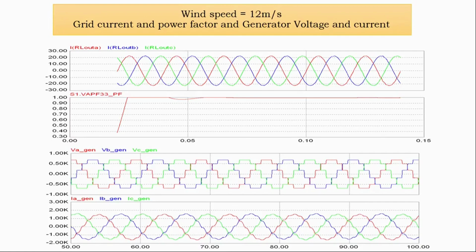Obviously at that time the pitch angle is 0 or a minimum, through which it will rotate, and we will get the sinusoidal current that is penetrating into the grid, and that is our power factor. As we have mentioned, in the grid tied system there will be only active power injection, so roughly our power factor is unity. I beg your pardon for the scale being cut over here. This is the time domain.